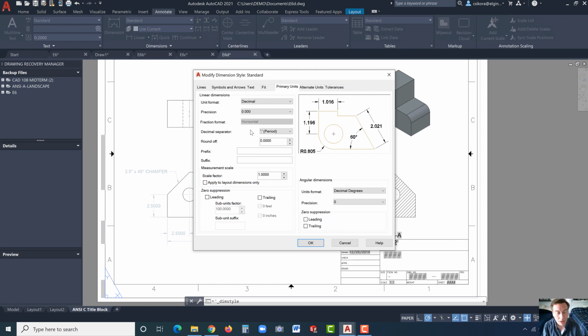Again, those of you entering manufacturing and engineering, when you work for a design company or a firm, a lot of times you'll hear thousandths, like 0.030 is 30 thousandths. 0.001 is 1 thousandth. Now, again, I always mention this in my classes. If you've taken math recently and never taken an engineering drawing class, that doesn't coincide with the terminology used in mathematics. So just be aware, they're very different. You could look it up, Google it if you want.